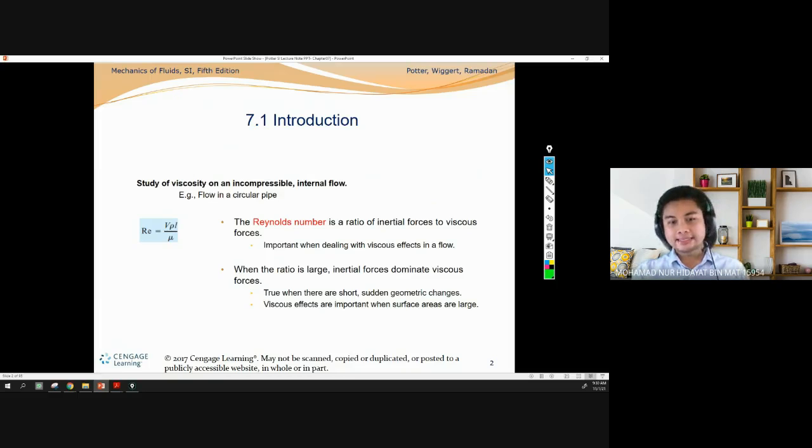Yes, another way is the Mach number. When you calculate the flow, the velocity or the Mach number shall be less than 0.3. That is the magic number. So when the flow is less than 0.3 Mach number, it is considered incompressible. So what happened when the Mach number is more than 0.3? Anyone please comment?